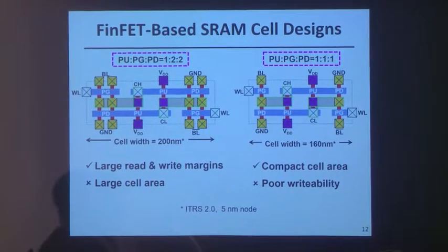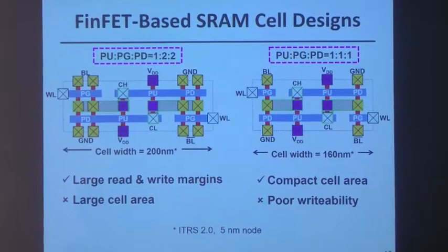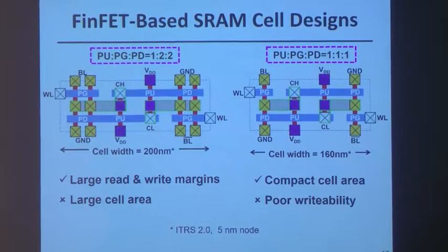But I wanted to come back to the SRAM cell. It turns out that for the SRAM cell, it's more ideal to have the pull-down and the passgate transistor be stronger than the pull-up transistor. Now for a FinFET, the crystalline orientation of the sidewalls is not 100, it's the 110 plane. And so that actually provides for higher hole mobility, but worse electron mobility. And for that reason, the strength of a P-channel FinFET is very close to the strength of an N-channel FinFET for the same fin dimensions. And so this is actually a problem for an SRAM cell.